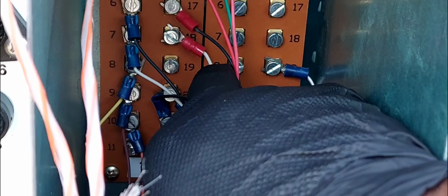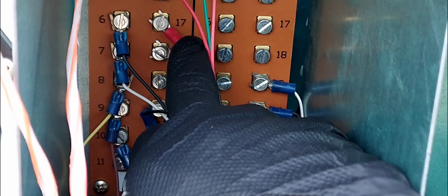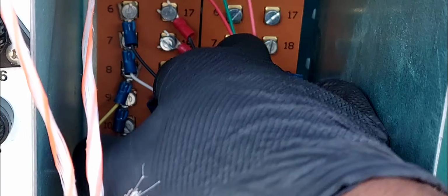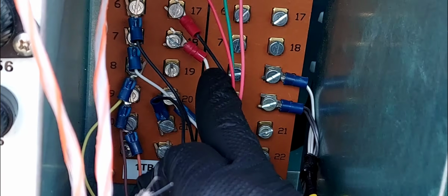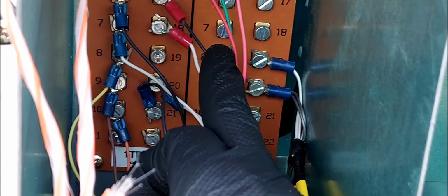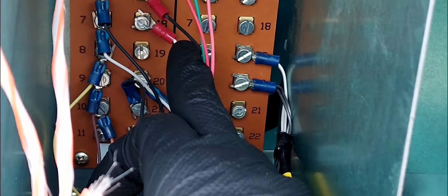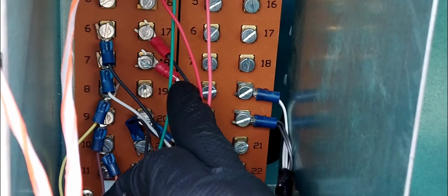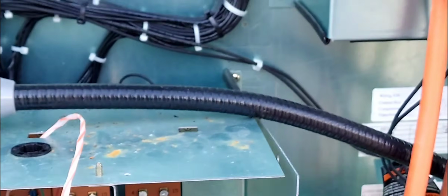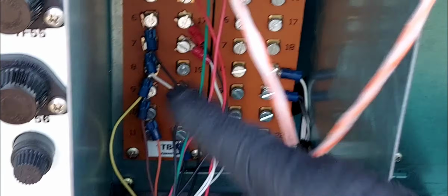As you can see, a white wire goes to 18, the black wire goes to 17. These two wires have to go back to a dry contact, like a relay contact or a switch, and if that is open, the machine shows external stop. So we're going to go ahead and test to see if there's potential across those two terminals.